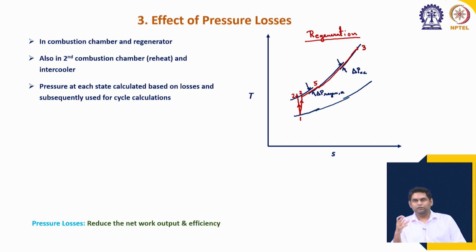So, there are devices which block the flow within the combustion chamber, as we will discuss later, and these are used for creating local pockets. These are known as flame holders. So, this creates local pockets where the airflow velocity is quite less and the flame can be sustained, and then the combustion can proceed. So, as a result these are necessary, but create some pressure loss due to drag.